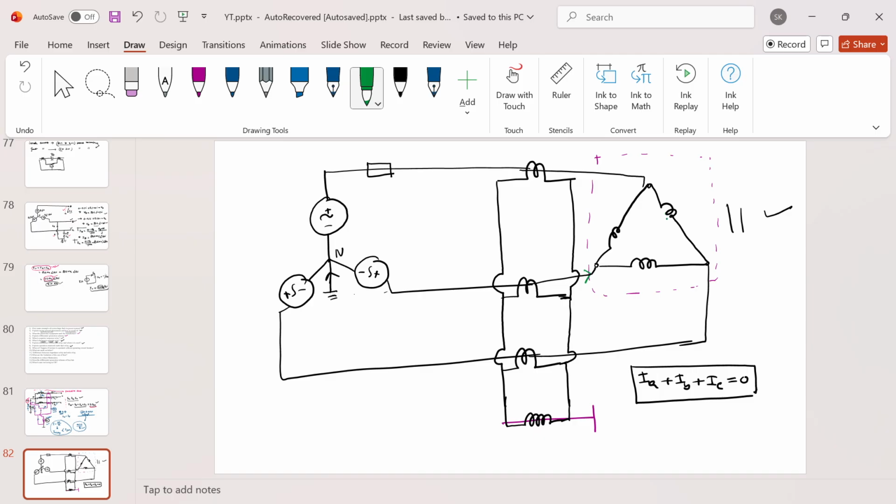Let's say you got a fault inside the protection zone. Now this fault current can complete its path through the source neutral. Now the current flowing through these lines IA, IB, and IC can contain the zero sequence component of current. Why? Because now there is a return path. So obviously my zero sequence component of current flows. So my neutral current and this fault current will simply be equal.